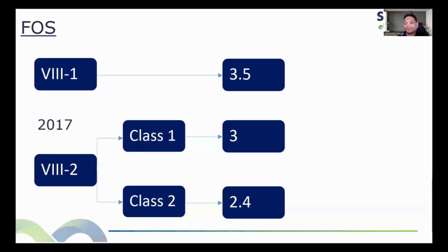Roughly 30%. See, if the size of the material is large and pressure is high, that means thickness is also large. In that case, 30% saving means a lot, right? So for bigger size equipment with pressure roughly more than 20 to 30 bar, it starts making sense to design it with division 2. These things are not written, but size is also a very big part.